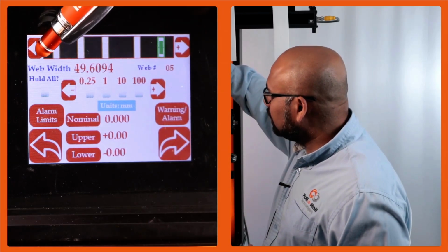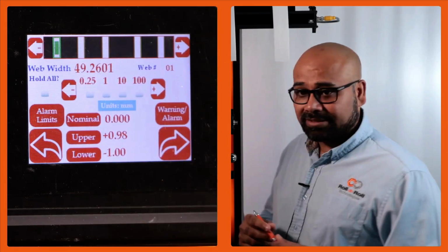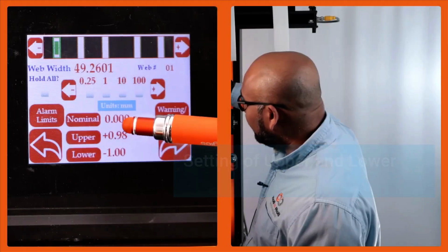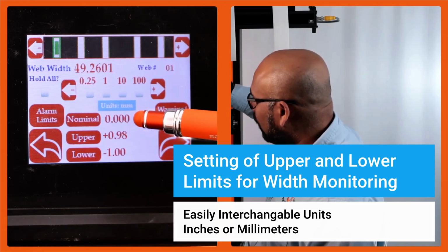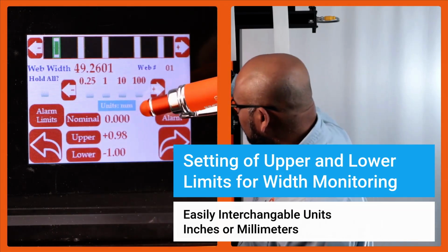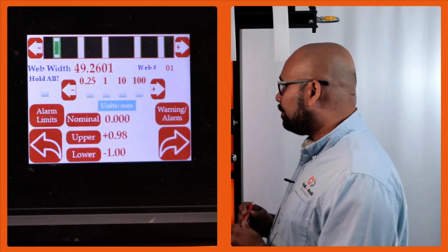These two icons on the top allow you to scroll through the webs. In this case, we are looking at multiple webs. For each web, we can set an upper limit, a lower limit, and a nominal width. The units are in millimeters. If we change the units to inches, then everything will show up in inches.